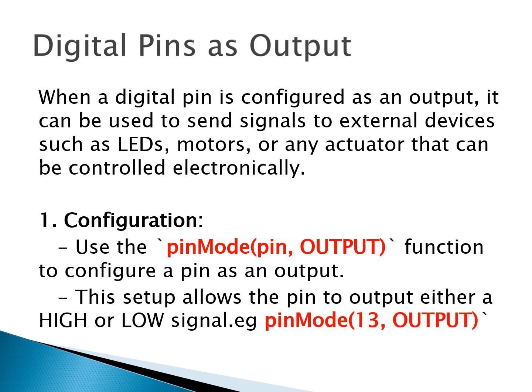Configuration. Use the pinMode(pin, OUTPUT) function to configure a pin as an output. This setup allows the pin to output either a high or low signal. Example, pinMode(13, OUTPUT). 13 means the pin number.